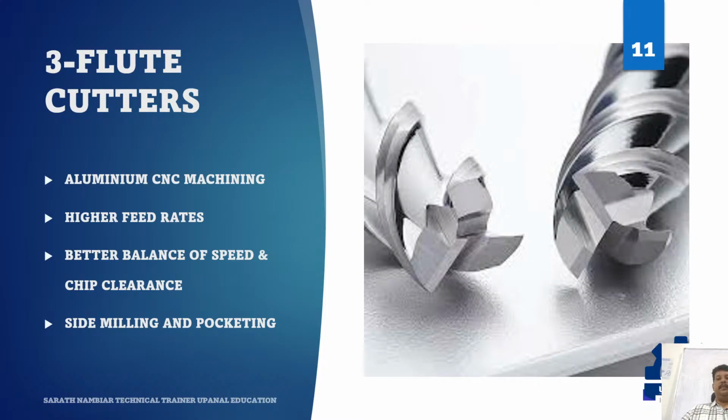At the same time, it still keeps good chip clearance space, which is important in aluminum machining. So many machinists consider three flute cutters the middle path between chip evacuation and productivity. They are commonly used in pocket milling and side milling, adaptive toolpaths, and production jobs.